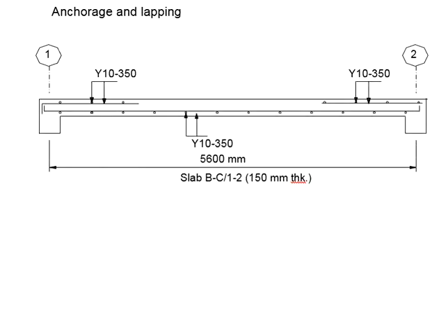This leads to an understanding that when sketching the reinforcement bar in the slab, you have to pay attention to the arrangement of the reinforcement bar. Know which layer of reinforcement bar should be at the bottom and which should be on top of the bottom reinforcement bar.